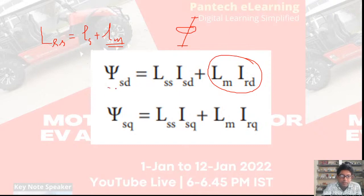So the stator direct axis flux is the total inductance into stator direct axis current plus mutual inductance into the rotor direct axis current. Similarly, the quadrature axis flux is equal to total inductance into stator quadrature axis current plus mutual inductance into the rotor quadrature axis current. Okay, so this is called the stator flux equations.